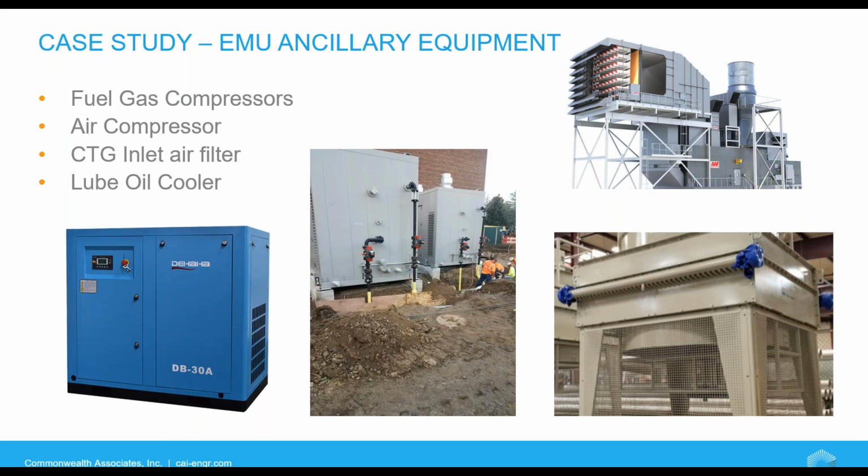At that time, they also did evaluations on performance to determine if a single set of compressors could supply the entire plant with the needed pressure, or if maybe they needed smaller compressors that would just handle the controls and the air tools and get larger compressors for the CTG air needs. In the end, it was determined a single set of compressed air system was installed.